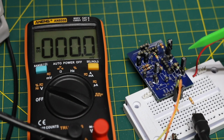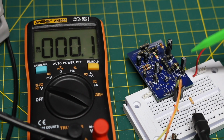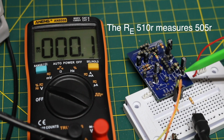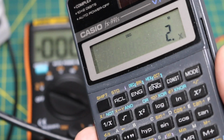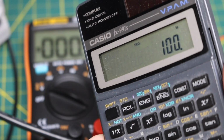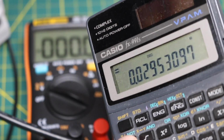With this capacitor now as part of the emitter impedance, we need to calculate its reactance at 100 hertz and 47 micro. Calculate that in parallel with this 505 ohm resistor. So XC is 1 over 2 pi FC. So 2 times pi times 100 hertz times 47 micro, 1 over that.